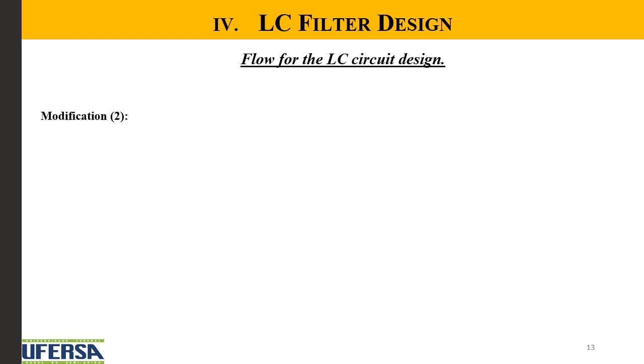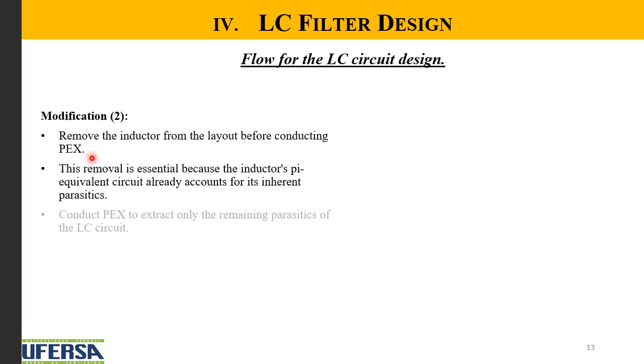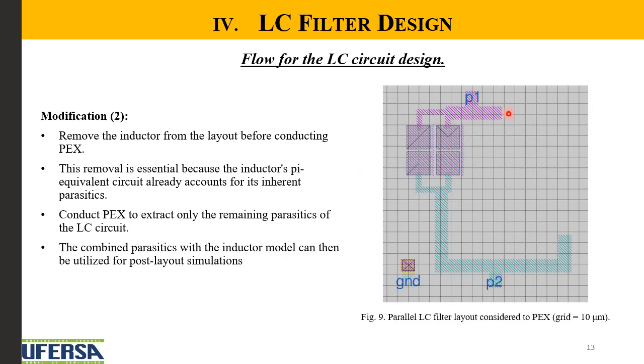The second modification is about the PEX, where the inductor was removed to run the PEX because the parasitics of the inductor are already in its pi equivalent.